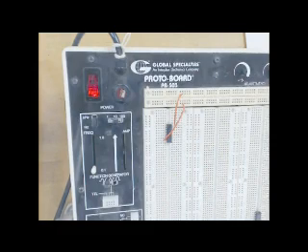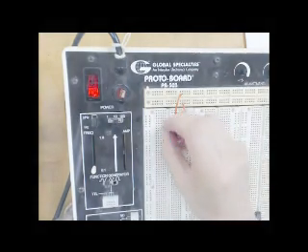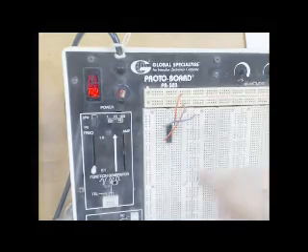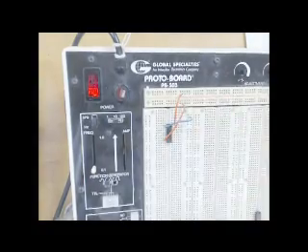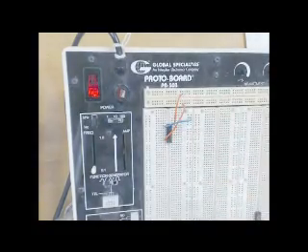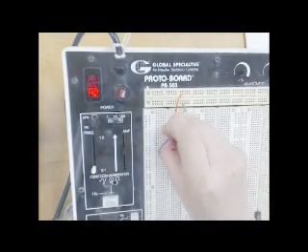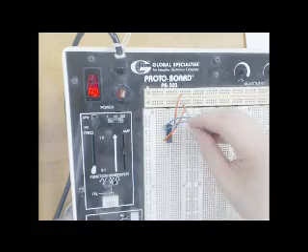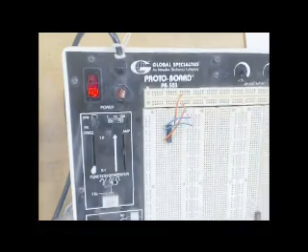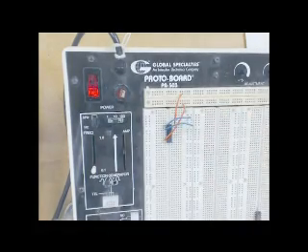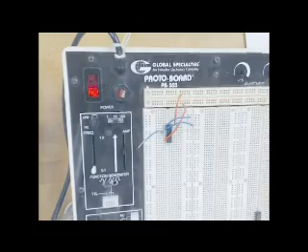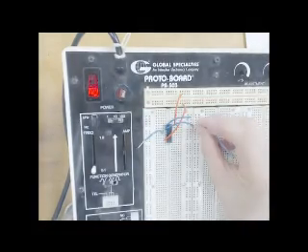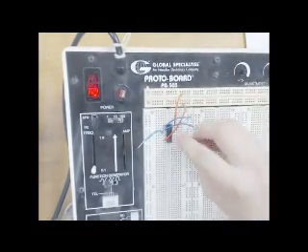And then simply, you would just start putting things in the pins. So for example, this will feed from A, which we've electrified as this strip here. So A will go into one, and B will go into the other. So this goes into the second one, and we have B. And then the output of these two, which will come out of this pin right here, is A and B. And the next one we want is C, feeding into another AND gate,